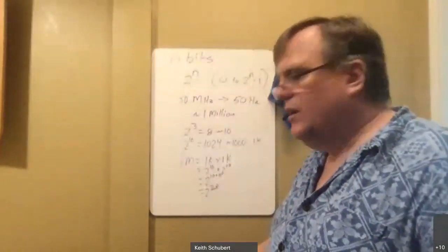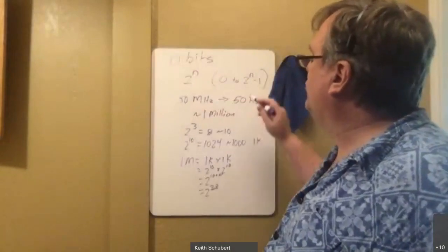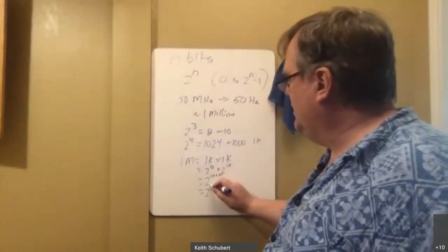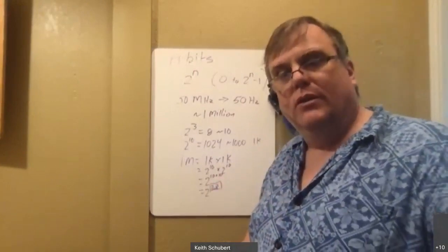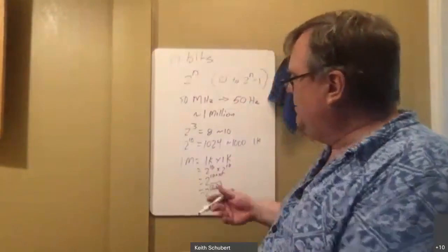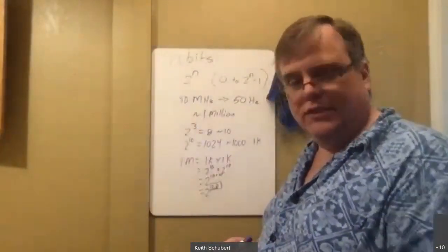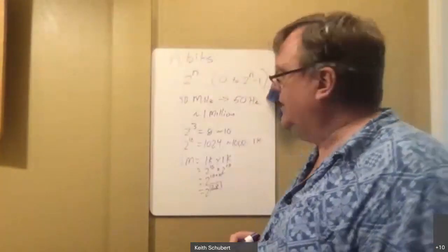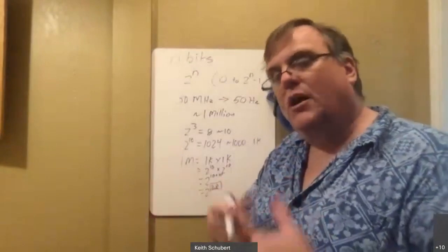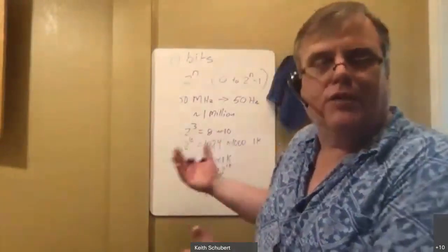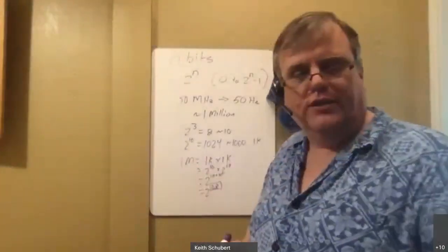So I can look at that and say, oh, to go from 50 megahertz to 50 hertz, I'm going to need somewhere in the ballpark of 20 bits. Now, I might need a number a little bit less than that, but you always want to overestimate. This is why we overestimate, because I'm going to count to here, and then we'll have some unused states, but I'll at least have enough states. And I will prevent the unused states from happening.